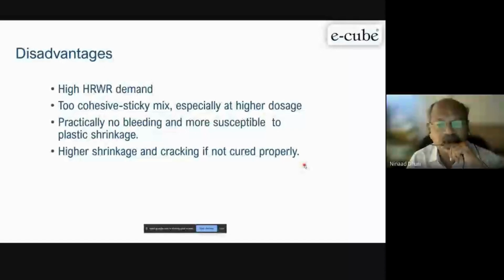But nowadays, most of the concrete where you are using 53 grade cement, where reaction starts very immediately, and using some admixture, the water cement ratio, the water binder ratio, is very low. There's a possibility that we are using low water content and the surface water may evaporate because of the ambient temperature and ambient humidity. There's a possibility you get shrinkage cracks.